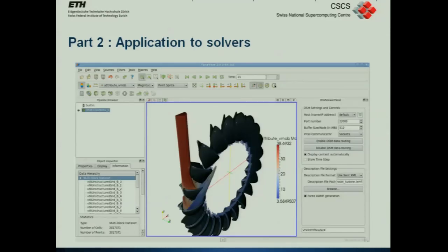And the turbine people, for example, how does it look when we use it? Well, essentially, we've bolted everything into a ParaView interface. You start the simulation. In fact, we've made it so that when you connect up here, you can basically click a button, you can submit a Slurm job onto the thing, it launches the solver, it launches the DSM host, they connect, everything connects back to the ParaView, boom, and you instantly get it.